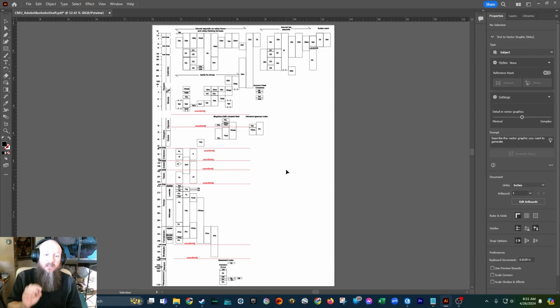That's the comment I'm going to start with: as a TIFF, sorry, as a TIFF, to get this as a TIFF so that we can easily get it georeferenced, and then go through the process of digitizing this in a GIS. So first and foremost, we can see that this has a width and a height of something like 13 inches by 16.5 inches for our page size.